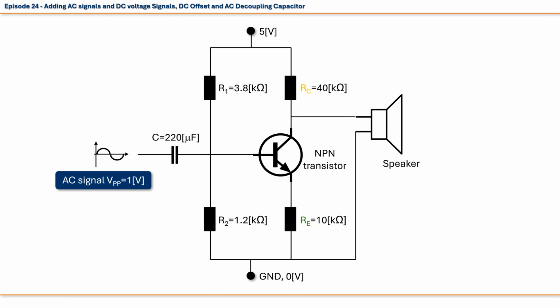Now, you might be tempted to take a speaker and connect it to this amplifier. That would not be such a good idea. Do you know why? Even though our AC signal is now significantly amplified, there are some problems. First, this circuit doesn't have enough power to drive a full desktop passive speaker. Maximum current that this configuration of amplifier can provide is around 47 microamperes.